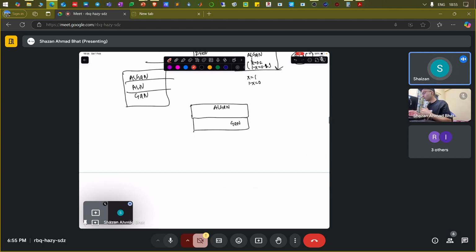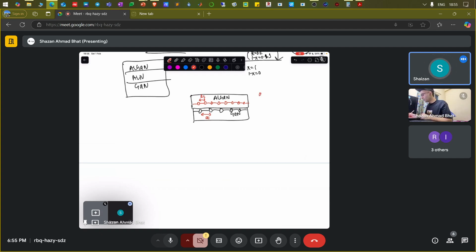Well, it turns out it's not always permissible, because if you have gallium nitride that has atoms lined up something like this, and the aluminum gallium nitride has atoms something like this, not smaller atoms, the lattice constant is smaller. Let's say the lattice constant here is A1, and for the AlGaN it's A2. That means A1 is greater than A2.